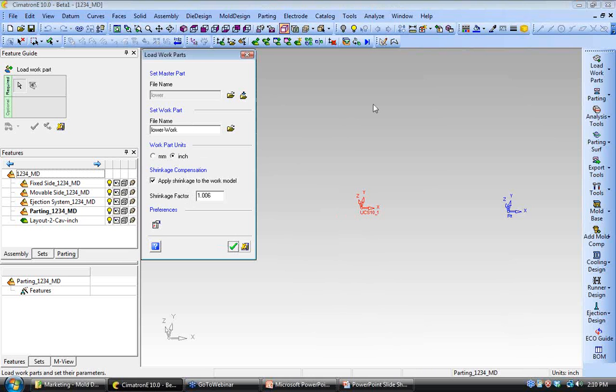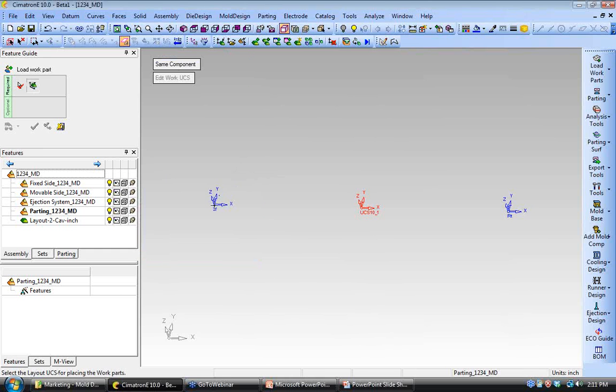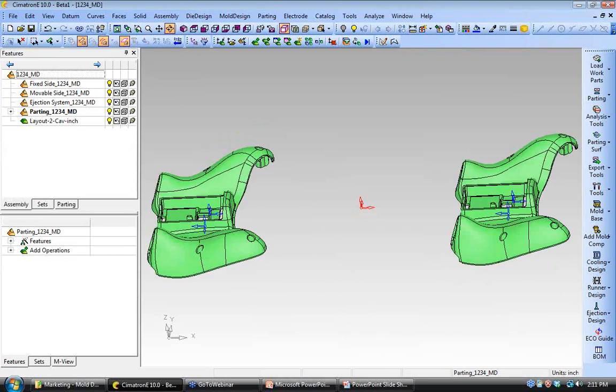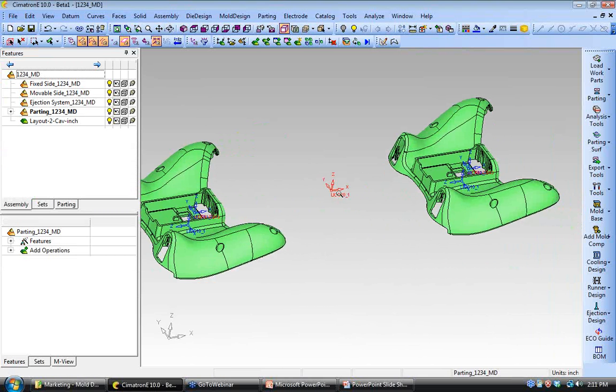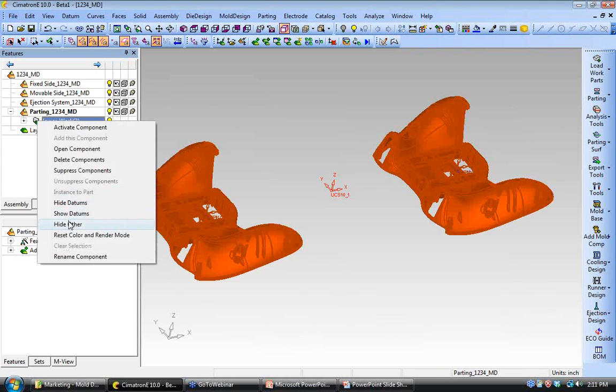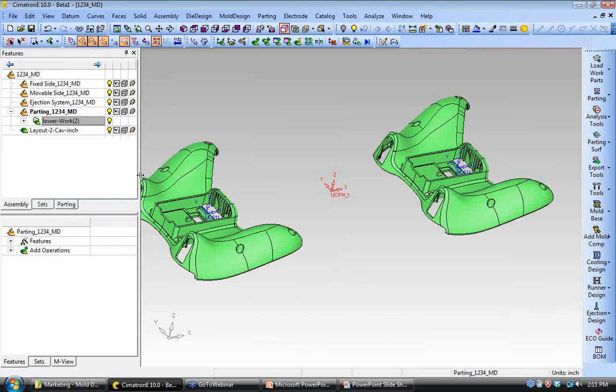The 2-cavity template that we chose has provided 2 points on the screen to use. And that gives us a start on where the mold cavities are going to be. At that step, we can tilt the parts for draw direction, but again, I already have the part set to pull in Z. But by adjusting those layout points, the parts can be arranged in the mold in any fashion.